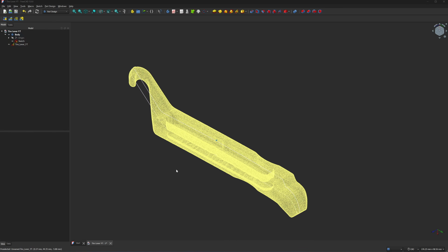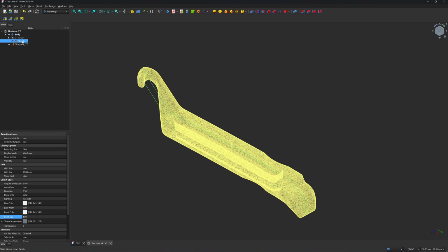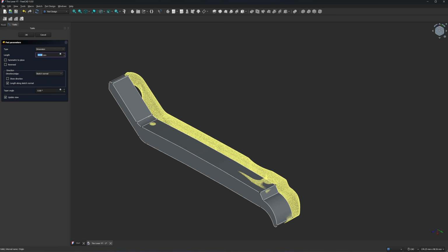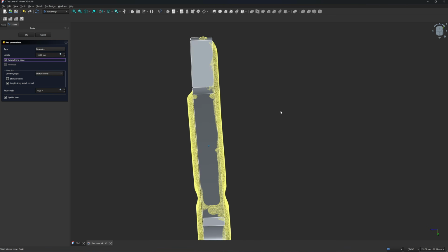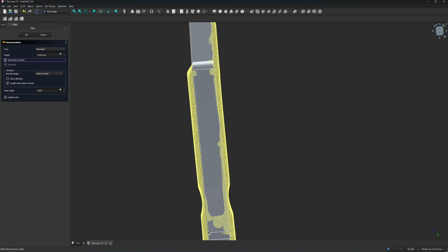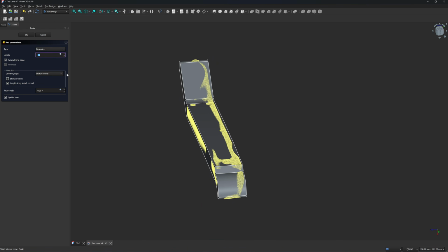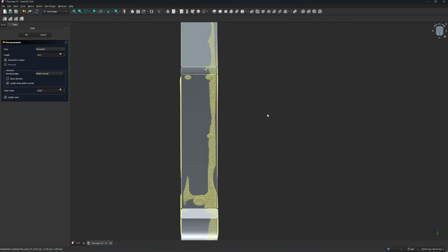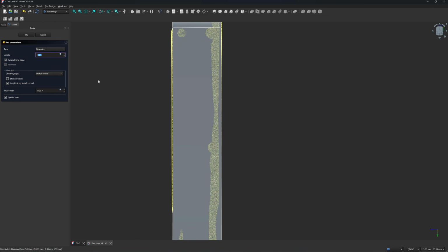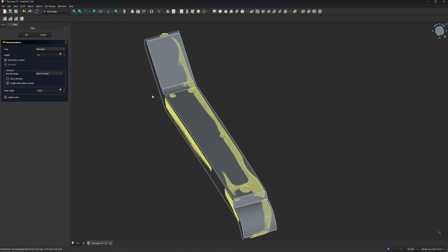Okay, next I'm going to extrude the profile. Click on sketch. Click on path. Okay, I click on symmetric to plane, so it's in the center. And then I'm going to change the size to 15. Actually, it's a little bit less than 15. 14.5. Yeah, it's 14.5. Now let's try 15. Doesn't matter. I just round it up to 15.